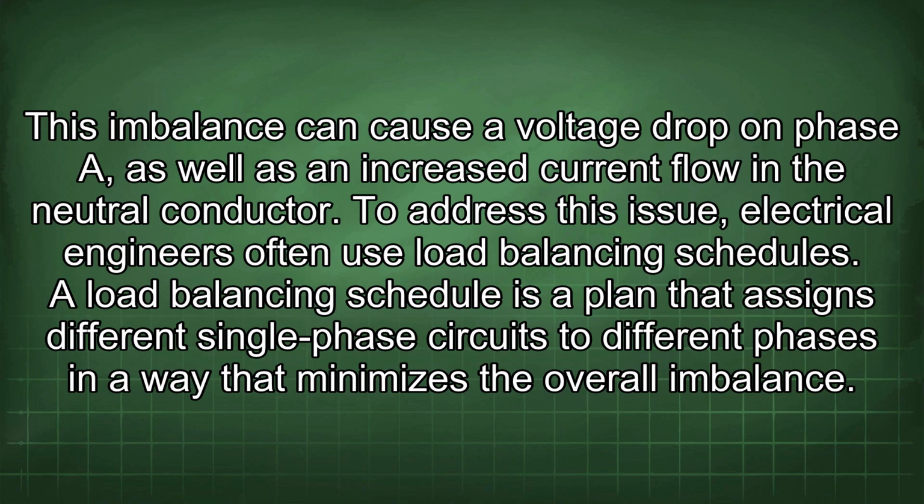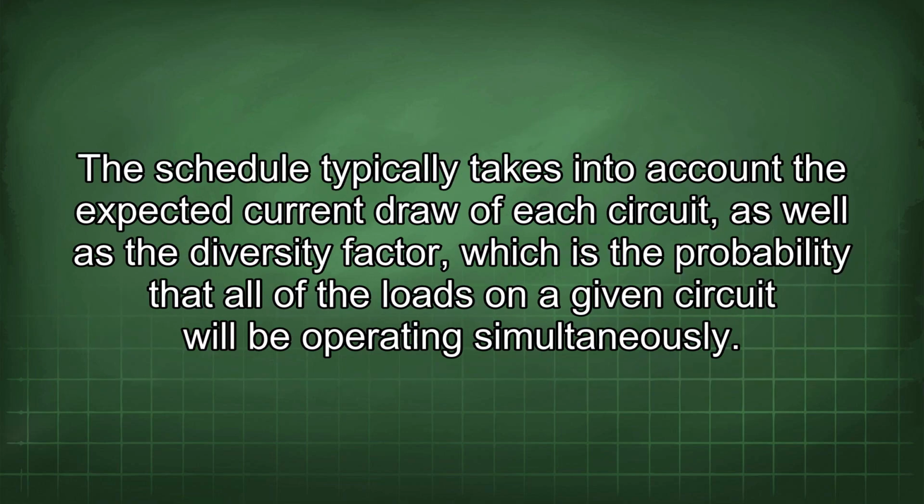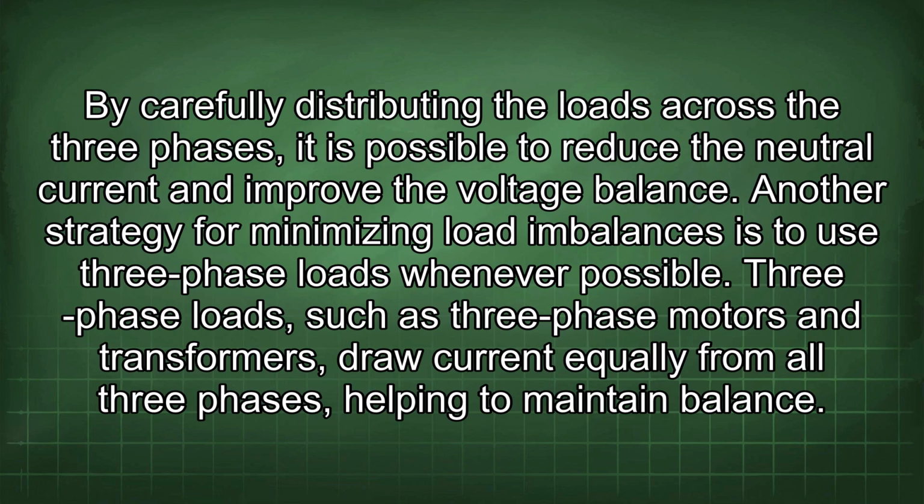To address this issue, electrical engineers often use load balancing schedules. A load balancing schedule is a plan that assigns different single-phase circuits to different phases in a way that minimizes the overall imbalance. The schedule typically takes into account the expected current draw of each circuit, as well as the diversity factor, which is the probability that all of the loads on a given circuit will be operating simultaneously. By carefully distributing the loads across the three phases, it is possible to reduce the neutral current and improve the voltage balance.